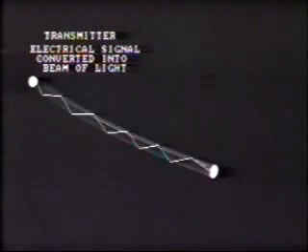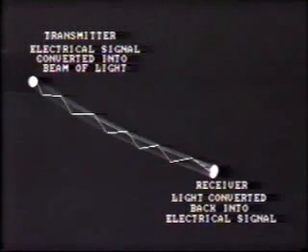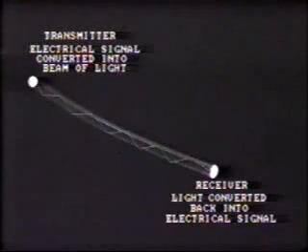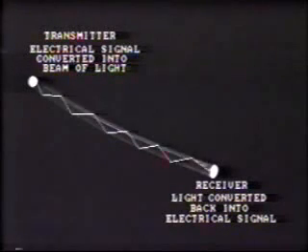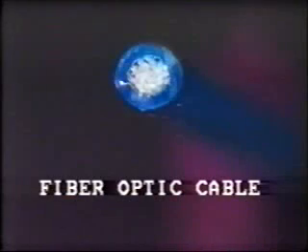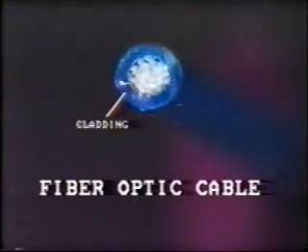The signal is able to travel around bends, providing they are not too acute. At the receiving end, the light beam is converted back into an electrical signal to initiate action, say tripping of a breaker. Obviously, the inner surface of the fiber has to be reflective, and its surrounding cladding is specially made to prevent or at least reduce loss of light.